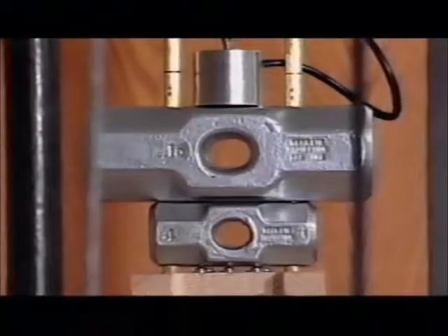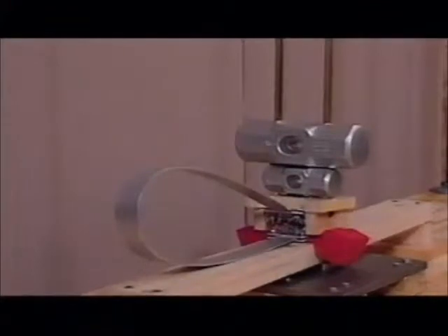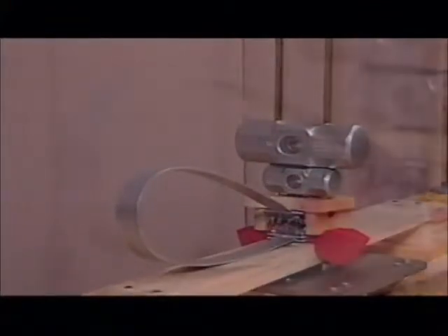Now the same test with the 20 pounds of weight. Again, pressing the button. Note that in fact, the column has indeed buckled as predicted. We do have a very large deformation. And the bar has contacted the floor, forcing it into the final shape.